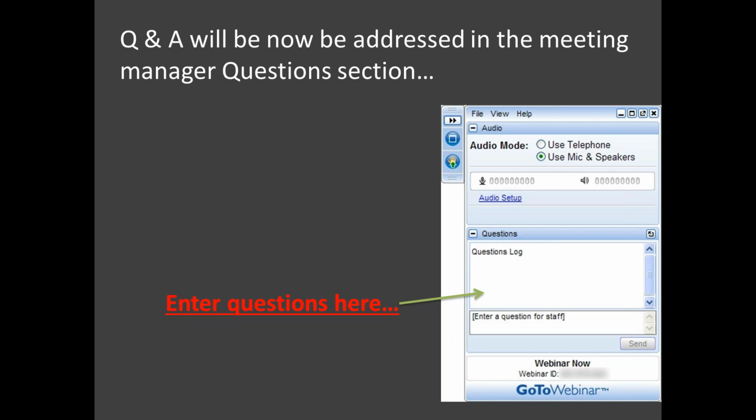What I would probably do in that situation is create an iPart of it, and depending on your setup and your workflow, I would quite possibly add that iPart to a custom content center library for everybody to pull from. There's pros and cons with using just iParts or just using content center parts. Either way is going to work. You just got to figure out if the cons are going to bite you bad enough of each one of them.